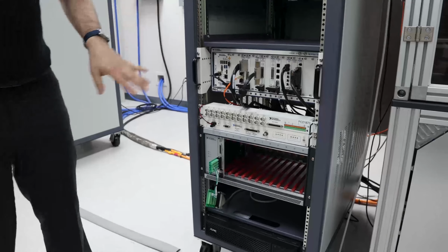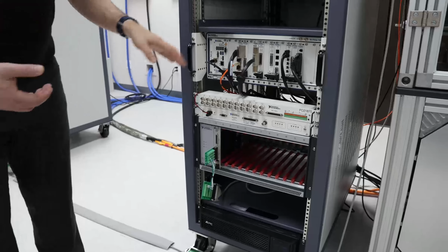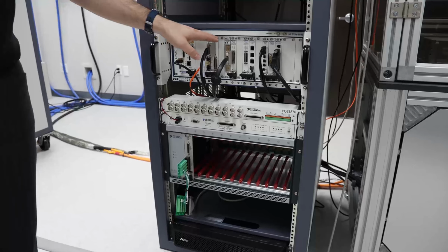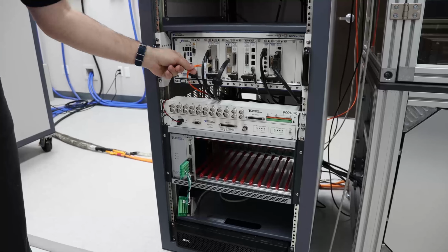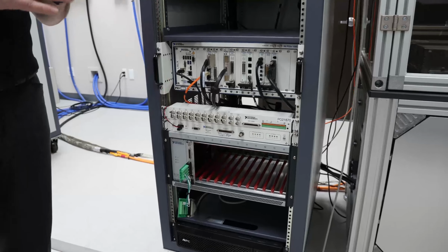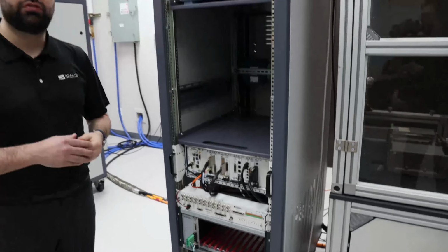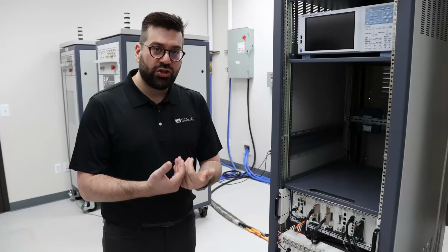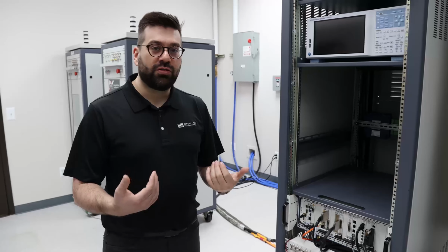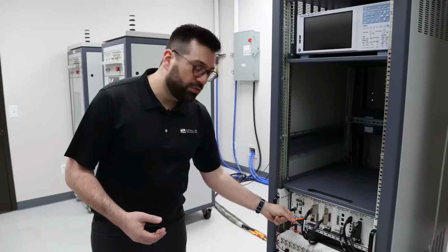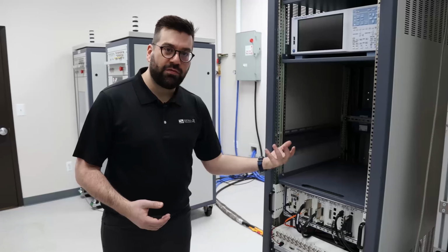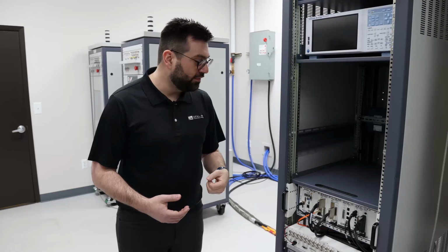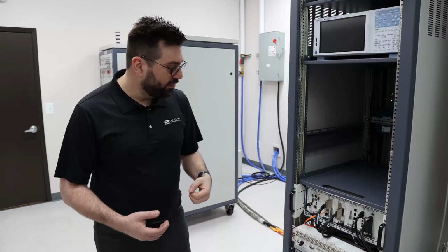From here, the main important component is really to have the controllers for the real-time application, and we provide the FPGA for the SFP communication. The SFP is the single fiber link that we need to connect to the DNV equipment. So the OPAL-RT FPGA model of the machine, either a PMSM or induction machine, is controlled by the fiber optics back and forth. So we receive all the measurements, and we close the loop with the amplifiers of DNV to the inverters.